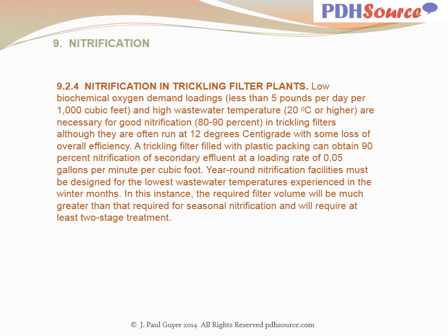0.05 gallons per minute per cubic foot. Year-round nitrification facilities must be designed for the lowest wastewater temperatures experienced in the winter months. In this instance, the required filter volume will be much greater than that required for seasonal nitrification and will require at least two-stage treatment.